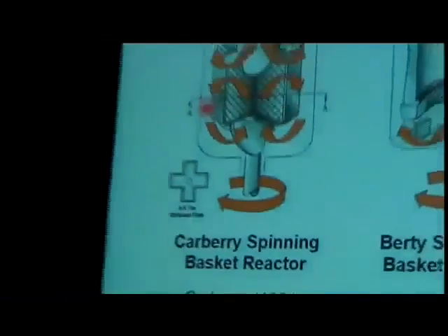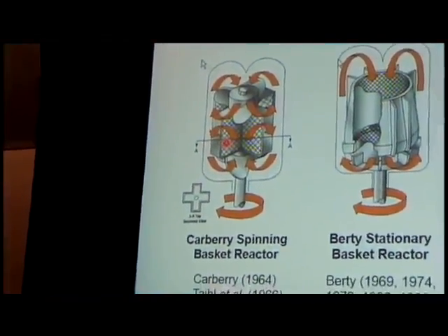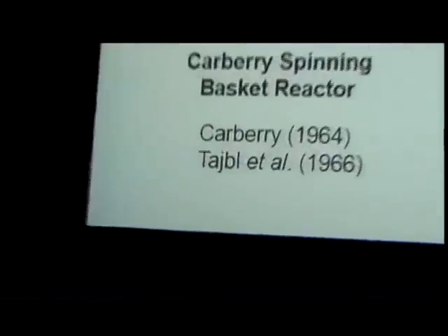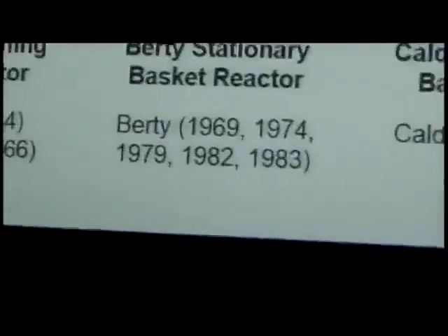Now, it was shown in some work that the Carberry design can actually result in some mass transfer deficiencies, because as the basket spins, it drags the gas along, so the difference in velocity between the particle surface and the gas is not very large. That can result in some mass transfer limitations, but it actually led to the Caldwell and also to the Berty types of designs.